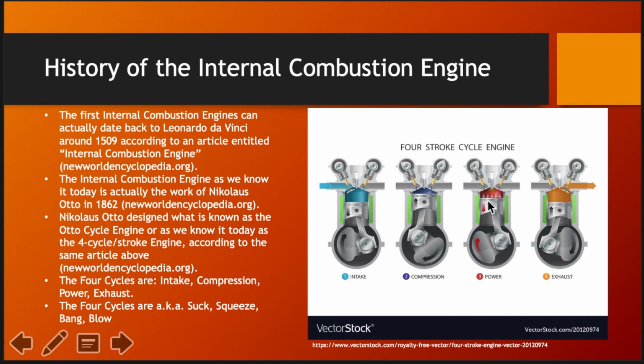Next is the power cycle. So basically, once this gets up here to top dead center, everything is in line. The rod, the piston rod, and the crank are all straight up and down. And here you have the power stroke. So the spark plug fires off the fuel air mixture under high compression, driving the piston back down, and the crank moves around. And then as the